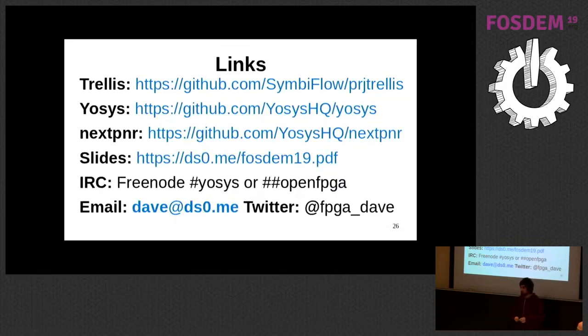You mentioned RAM, is DDR3 possible? Yes, the ECP5 has I/O that's definitely designed to support DDR3. I'm on the last stages of the open source tool support for that. My master's thesis is very much in the direction of getting the tools to a point where a DDR3 controller can work.